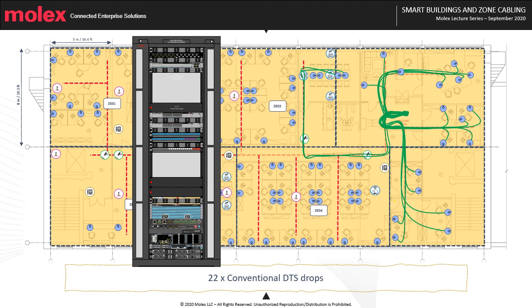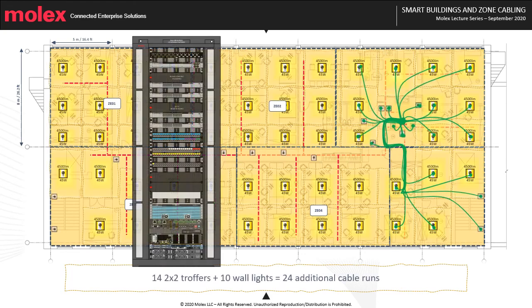And let's now continue and complete our cabling design, since all our remaining voice data and IoT services, along with our remotely powered LED fixtures, are all located near our main TR. There is no real need to have an additional zone enclosure here. All these devices will be directly connected to the TR. And this is for the distribution of our remotely powered LED fixtures.